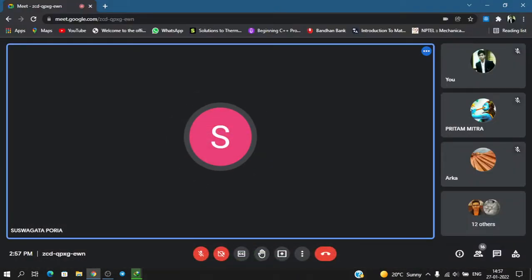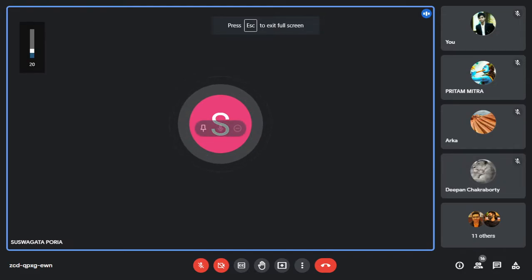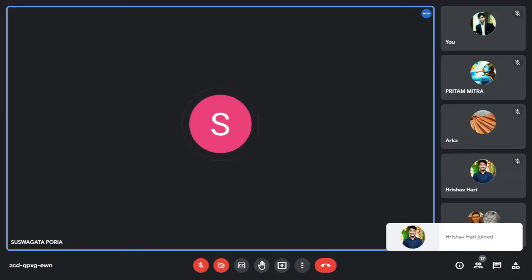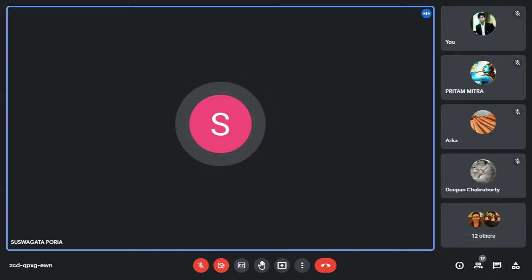So let's start. Before starting, I want to say one or two things. I have seen that some of you have already submitted the assignment, and I have noticed some common mistakes. That thing I should discuss first. First of all, when you put dimensions in your drawing, the numbers, 50, 60, 70, have a definite height and width which you can set in AutoCAD by using dimension style.